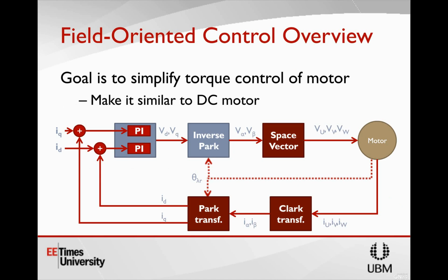So what the measured currents actually represent is the magnitude and angle of the current in the motor. And this is aligned with that stator magnetic field. So what the Clark transform does is it converts the 3 vectors into 2 vectors. And that's because the sum of any 3 vectors can obviously be represented by 2 vectors. And this is really done to simplify everything else.